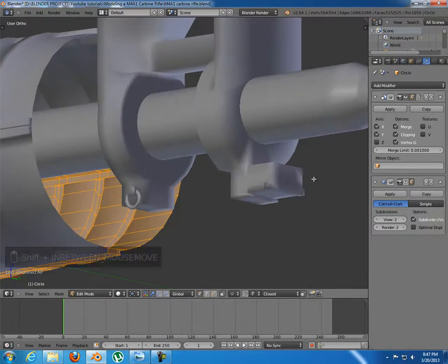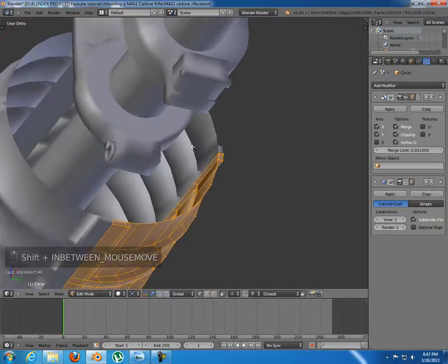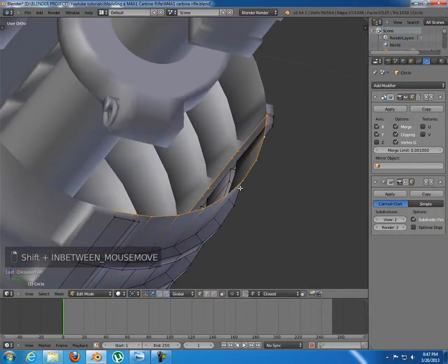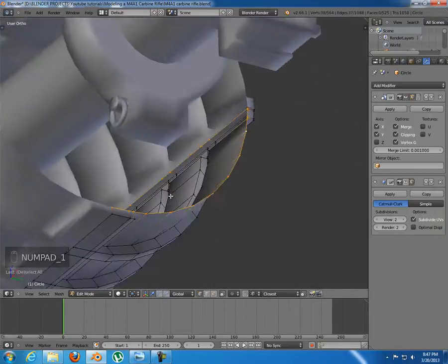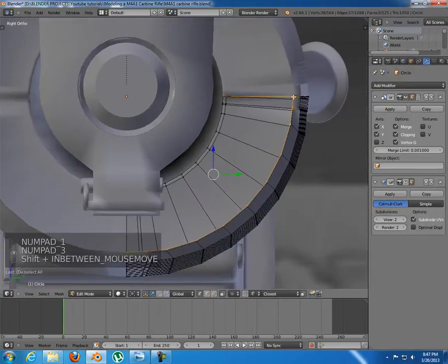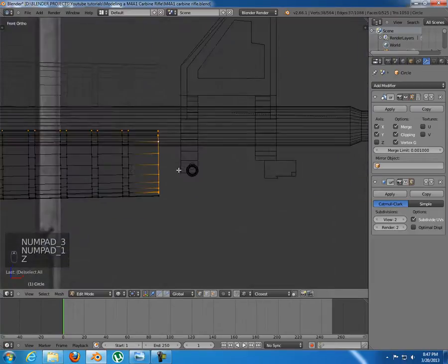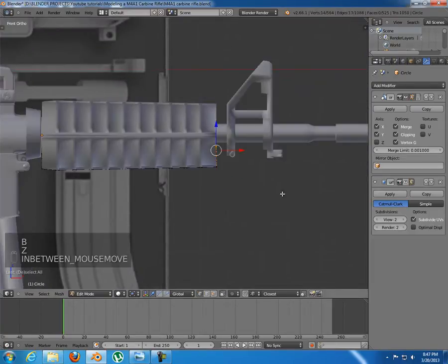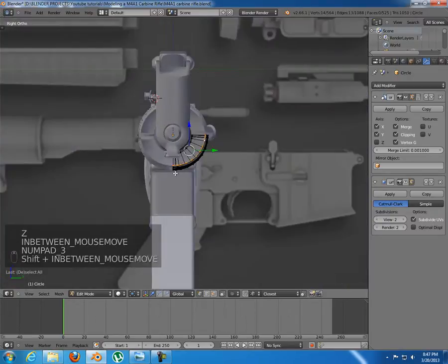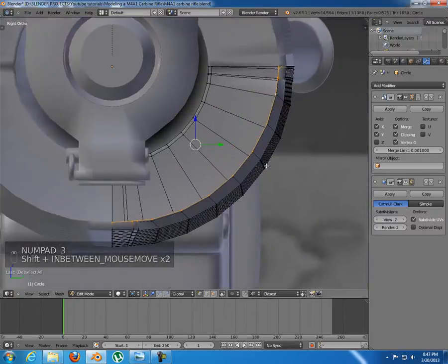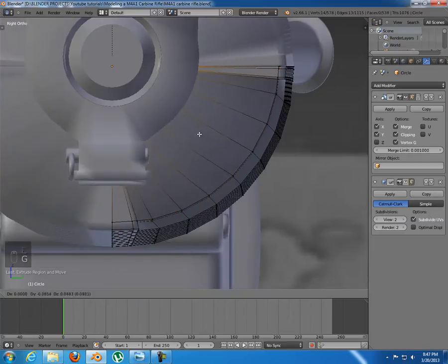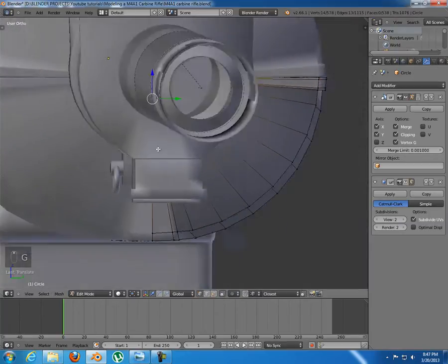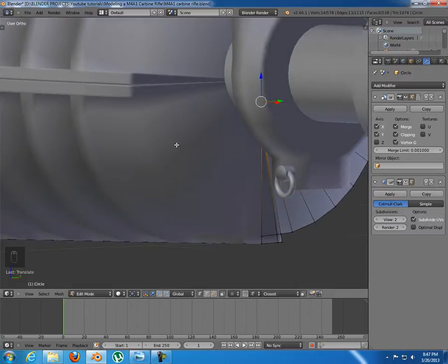So we have applied a mirror to there. So the way I'm gonna fill this face is I'll select that loop in there, but only those one that are right there on the front, and I'm gonna extrude it and take them all in as much as possible.